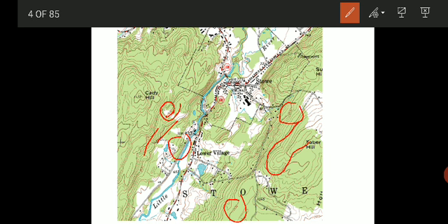Suppose the highest contour is at the center, say the contour value is 1122, here it is 1000, and it is decreasing, that is 900. So what does it show? The highest contour is at the center and the contours are decreasing away from the center, which shows it is a hill. The highest contour will be at the center and the values go on decreasing away from the center, that is the height above the mean sea level goes on decreasing.